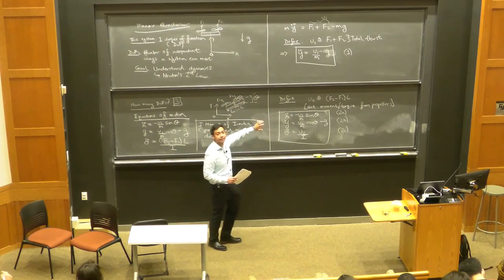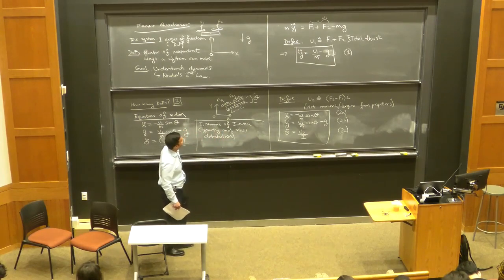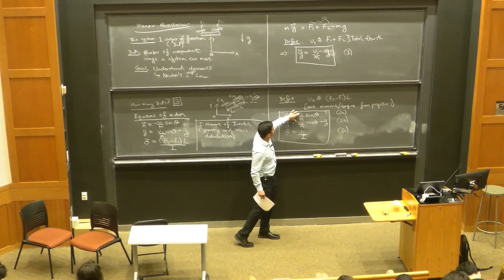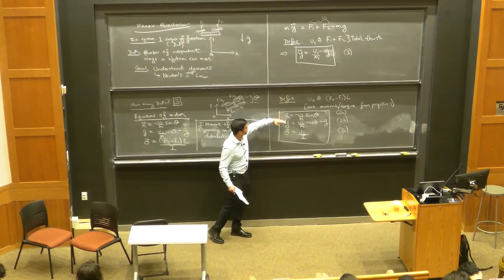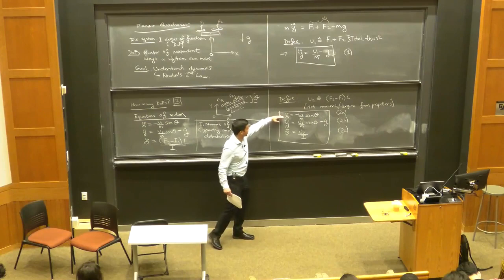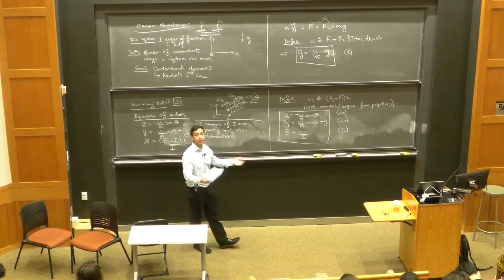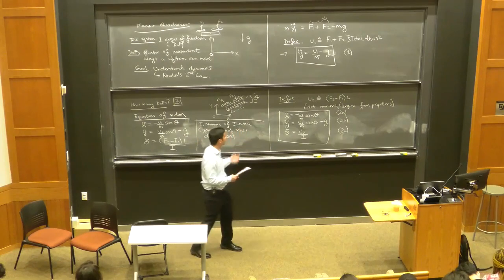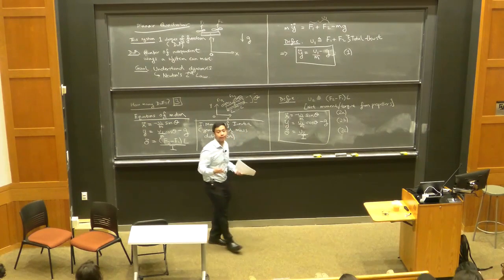So at a high level, these differential equations are telling us how the system moves, how it behaves. At a slightly more concrete level, we're saying that if I tell you what thrust forces are being applied, so that fixes U1 and U2, and I give you some initial conditions, some initial x, some initial y, some initial theta, and also some initial speeds, some initial x dot, y dot, theta dot, you can integrate these equations of motion forward, maybe using some computer software like Python, and that will tell you exactly where the drone is, what its orientation is going to be at any point in time.